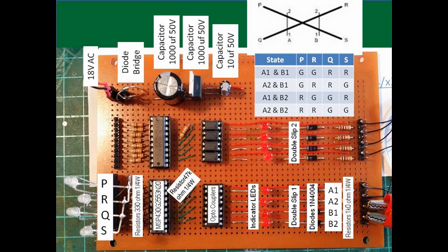The completed circuit runs through the resistor, the diodes, the indicator LED to an optocoupler, which is effectively an electrical switch for the microcontroller input. You can see in the bottom left the outputs P, R, Q and S. They are bi-coloured common cathode LEDs. All of my control panels have an 18 volt AC accessory, which is in the power section at the top, goes through a bridge rectifier, capacitor, then a voltage regulator for feeding the MCU.